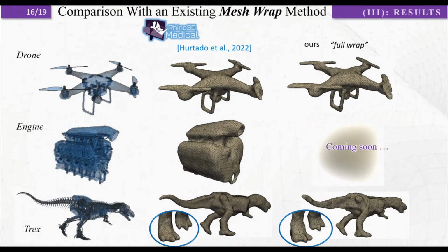The last insightful comparison is with the enveloping CAD surfaces by Hurtado and colleagues, who actually integrated their framework into Rhino. We compared their implementation with our isosurface shrink wrapper approach, useful for complex non-manifold target data with internal cavities, and we saw that it still needs some improvements, mainly by abolishing the use of isosurfaces and sticking to the convex hull or icosphere starting surfaces because of the inability to get rid of internal cavities.